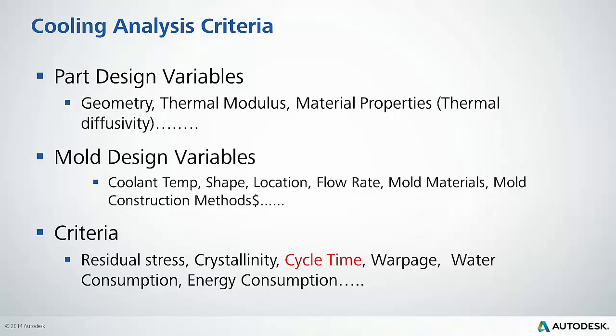bottom part of that equation is really the thermal bulk, right? And so we've got this equation that we can look at with materials in our database, whether it be polymers or core inserts. And this thermal diffusivity can be thought of almost as like thermal inertia. So pretty good thing to look at in this part design.